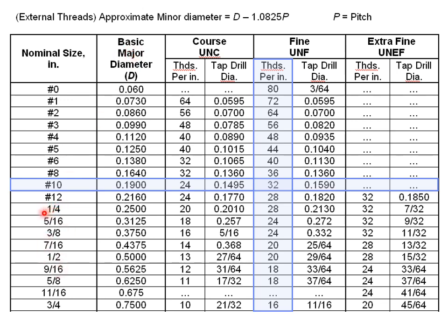If we order quarter, 1/4, that's 0.25 inches for your major diameter. And anything below 0.25, I forget what the formula is, but they use a formula now. If your boss asks you to order number 10s, it involves something like 10/64 plus some fraction, and it'll come up with this number. Same thing with these others. So there's a formula used to come up with these numbers and give you these diameters, which is not important. We can just always use the table here.